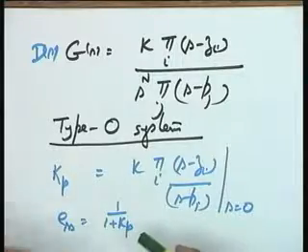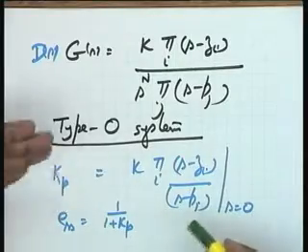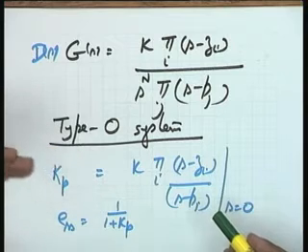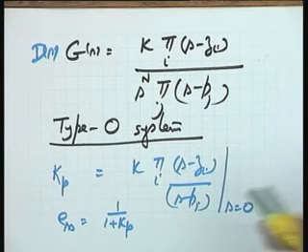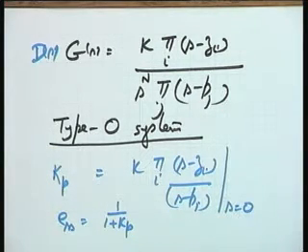So if high accuracy demand is there, as you will see, you will have to intentionally introduce integrators in the forward path. Okay. Is the table complete please? Kv is equal to 0 and Ka is equal to 0 and hence steady state error is equal to infinity. Anyone who could not get this point please? I hope this is okay with all of you. In that case I go to type 1 system please.